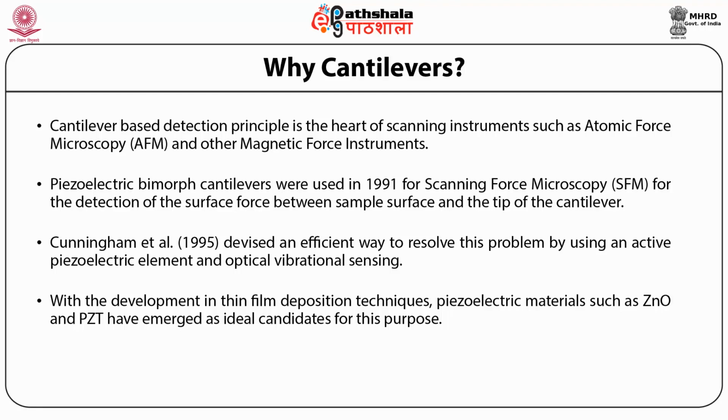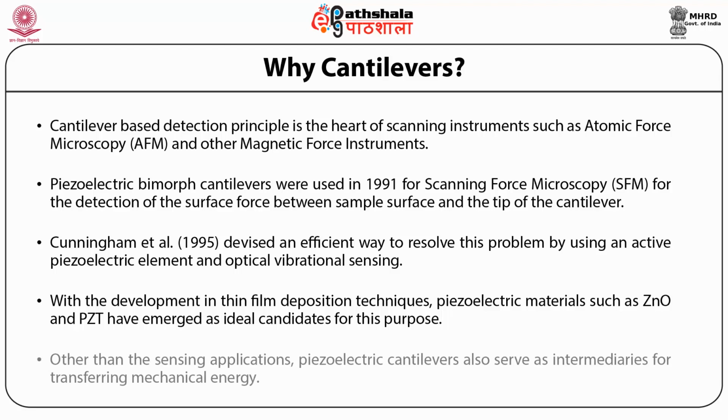With the development in thin film deposition techniques, piezoelectric materials such as zinc oxide, that is ZnO, and lead zirconium titanate, that is PZT, have emerged as ideal candidates for this purpose. Other than the sensing applications, piezoelectric cantilevers also serve as intermediaries for transferring mechanical energy. The mechanical energy due to cantilever motion can be converted into electrical energy via piezoelectric effect.